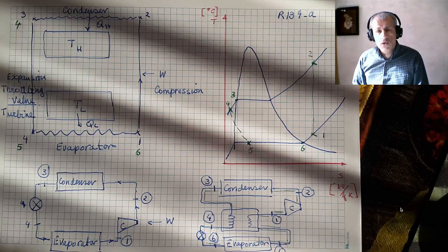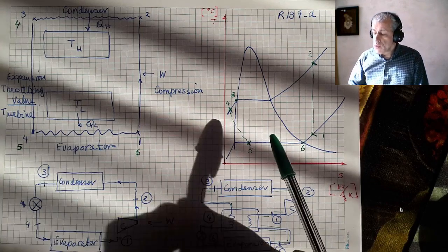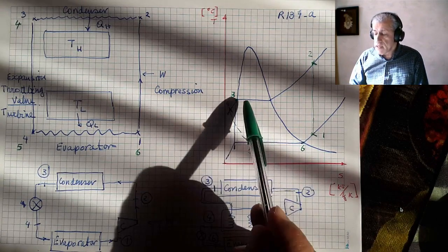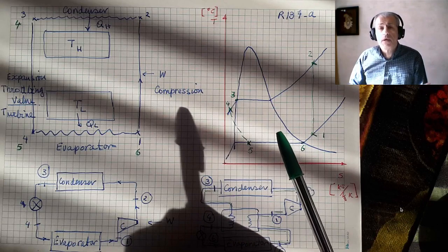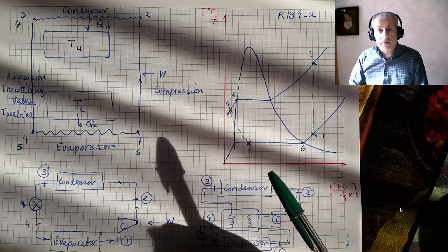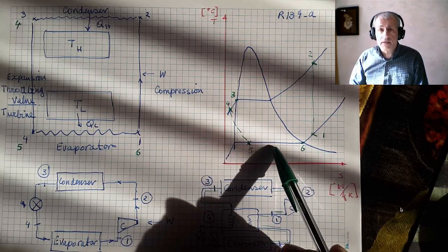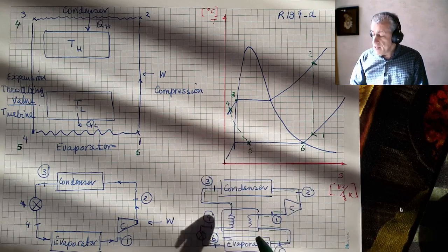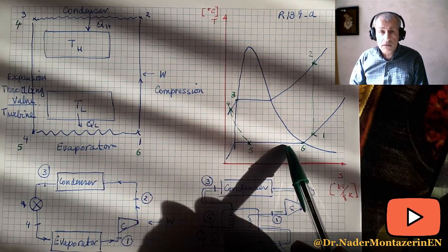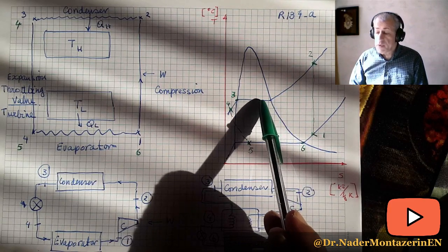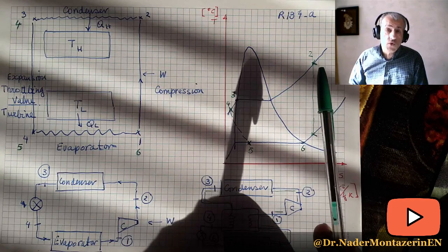What we usually do is work on two different pressures, which on saturated lines have, of course, some corresponding temperatures. Now, it's often said that they define evaporator temperature or pressure, but as far as the condenser is concerned, they call it pressure because they usually know this.